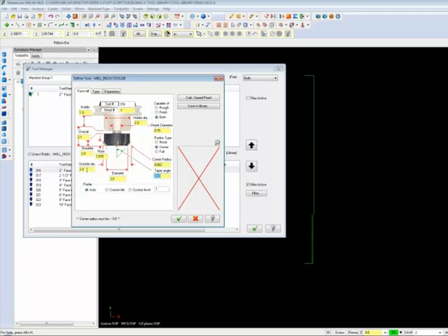Yeah, when I was going through this to rehearse the presentation, I even tried putting in a different outside diameter. Since it's got a corner radius and the inside diameter here is 2 inches, if we make the outside diameter 2.124, oh, there it works. That didn't work before, but I probably put the wrong outside diameter in. So you put the 2-inch outside diameter and then go to the inside diameter and make that a minus value.